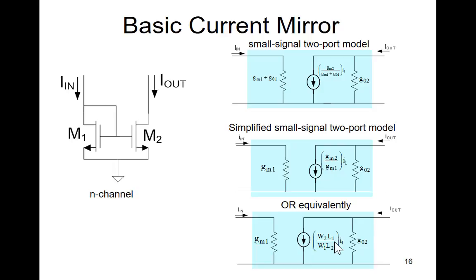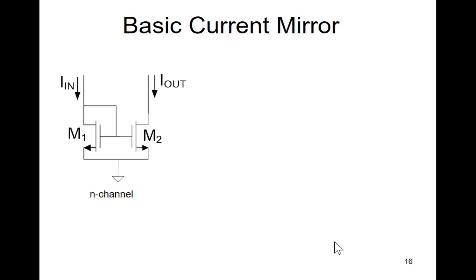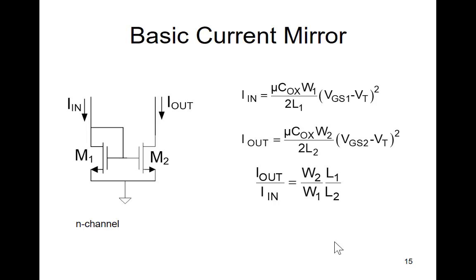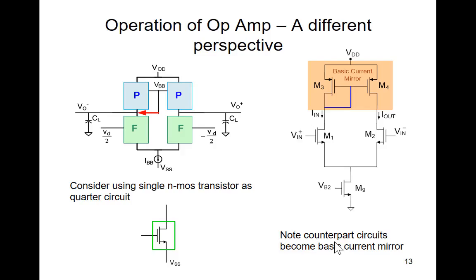Question? Yeah, I do have one. So you said we've lost symmetry now, right? I guess I don't see that because that current mirror is going to the gates of those PMOS transistors, right? So we're not losing any current going into those gates, right? First of all, the reason we've lost symmetry is if you look at the circuit to the left and to the right, we don't see the same thing. Sure. Okay, so that was why I said we lost symmetry. But now, what was your other question?